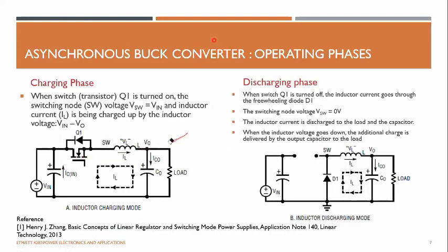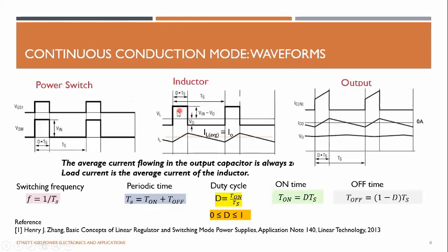So here, when the inductor is switched on, the switch node voltage becomes the power supply voltage, and the output voltage is V out. So the inductor voltage is V in minus V out. This is that inductor voltage. The inductor voltage is positive, so it enables ramping up its current.